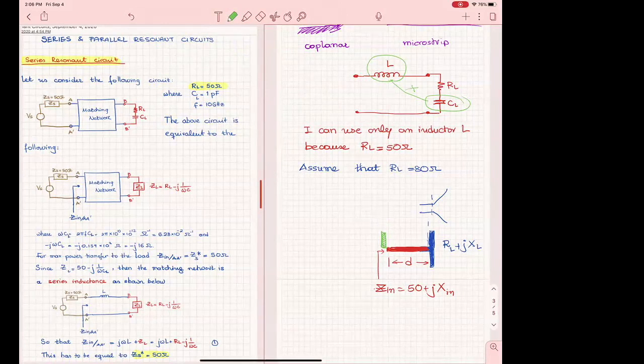All right, and then I will continue after that. And at that point, this one is my matching network right there. Because here, with what I've done, I have a Z in, which is 50 ohms. Is that clear? So I'm introducing this to you now, so you're thinking that you have flexibility where to put your stub, to the left or to the right.